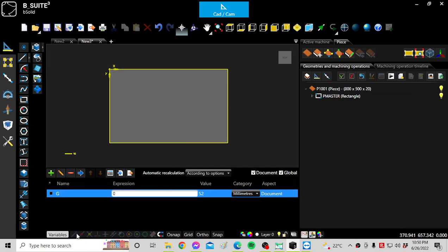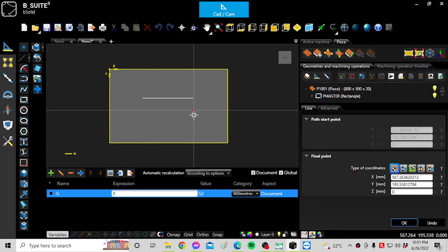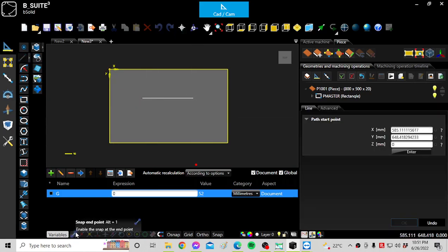Okay, down here we have very useful things like select points. For example, if I get a line here, then I go here, see, snap endpoint. Once I get close, it gets the blue point, and I press there, I know I can follow from there, see? If I press this one, it's going to be the middle. It's going to show me the middle of the lines.